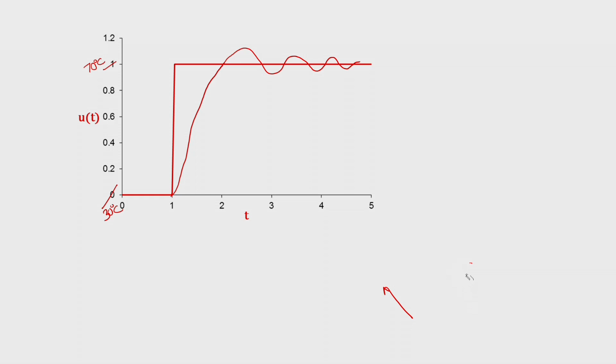So the final reading of 70 degrees Celsius that we are going to get is not 70 degrees Celsius in the measuring platform, mass measuring platform point of view, but 70 degrees Celsius for the thermometer. That 70 degrees Celsius that we are going to get from the thermometer, that reading may take a sufficient amount of time. Just think about what doctors advise while measuring the body temperature using a clinical thermometer. They generally ask us to keep the thermometer in contact with our body for a period of 1.5 to 2 minutes. So that will allow the thermometer column to settle down to the temperature of our body.